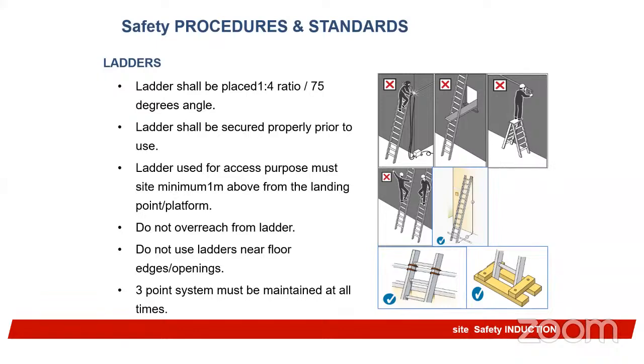3-point system must be observed at all times. That is, at any point in time, you should have either 2 legs and 1 hand on the ladder, or 2 hands and 1 leg on the ladder. At every point in time, there must be 3-point contact. Please let us continue.